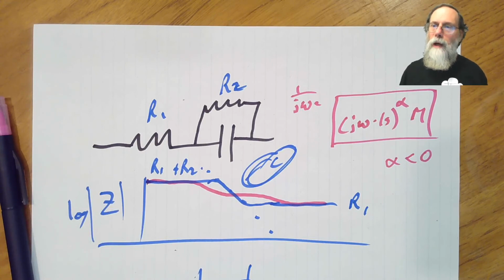So when you're modeling an electrode, first figure out what the electrode's doing, measure it, and then determine what's the appropriate model for what you've measured. And it'll depend on what frequency range you're interested in. If it's constant over the frequency range you're interested in, it's a resistor. If it's sloping down with impedance inversely proportional to F, it's a capacitor. If it starts sloping down but not at 1 over F, then you can use this capacitor-like model to capture its behavior.